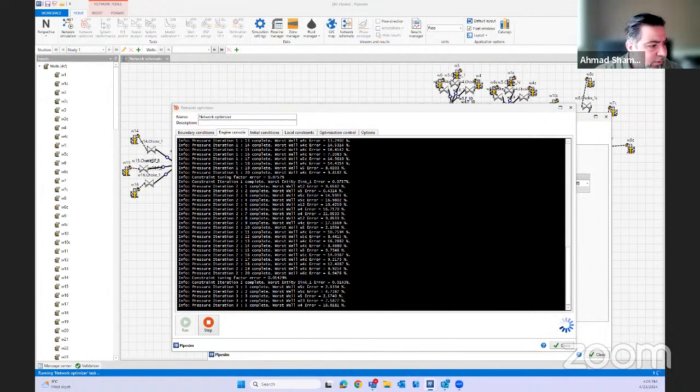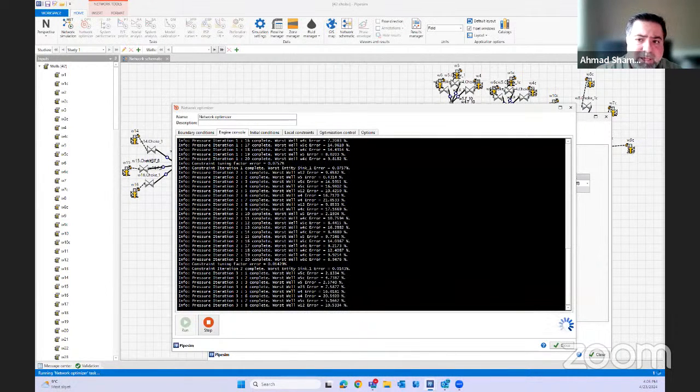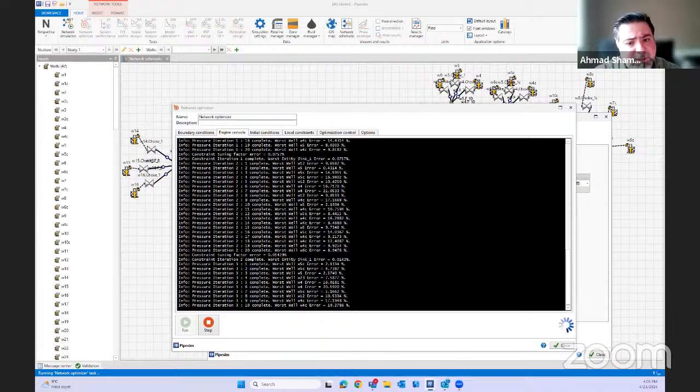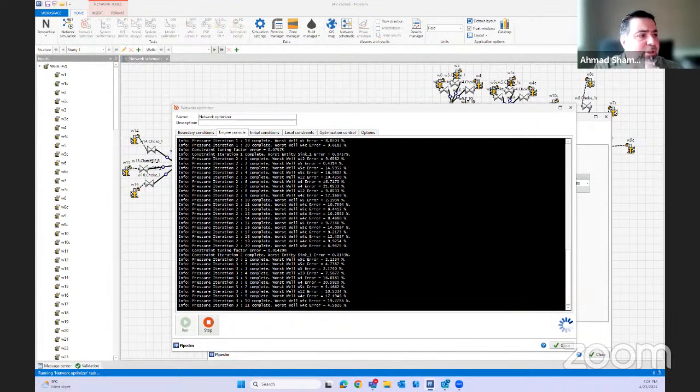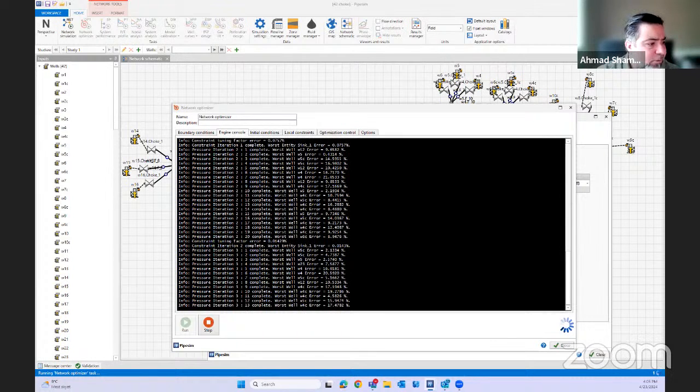When there are different hydrate curves for different chemical rates, how do you implement all of them in the simulation? Basically, at each node where you inject a different hydrate inhibitor, the composition will be mixed. Then it will come up with a new hydrate line with a new hydrate temperature, and then it will perform the calculation.